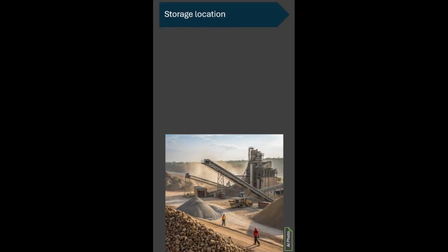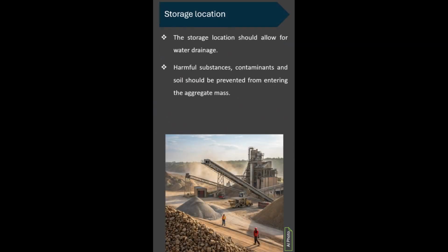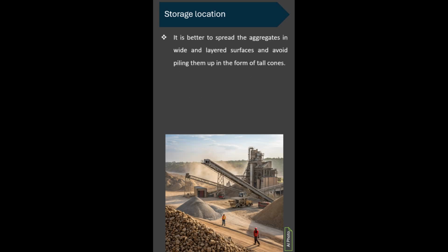Storage location. The storage location should allow for water drainage. Harmful substances, contaminants, and soil should be prevented from entering the aggregate mass. It is better to spread the aggregates in wide and layered surfaces and avoid piling them up in the form of tall cones.